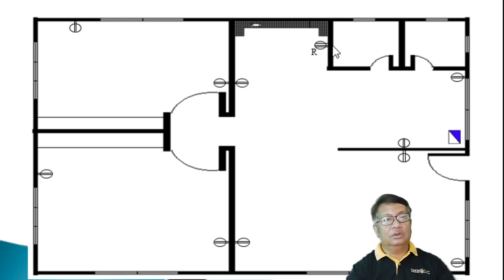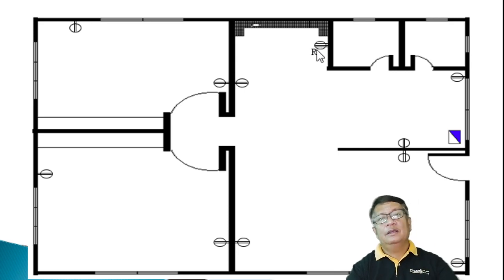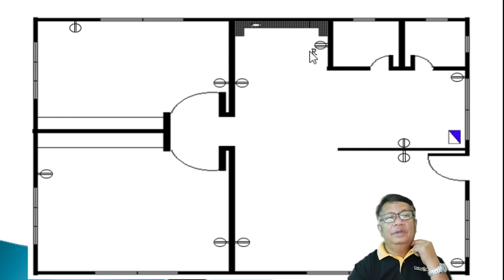What symbol are you going to use for this range outlet? Try to use a simple symbol like the convenience outlet, but write R here in this portion or anywhere on the side, so that you will know that this outlet is a special outlet intended only for this cooking device, an electric range, because all electric ranges should have a separate branch circuit.